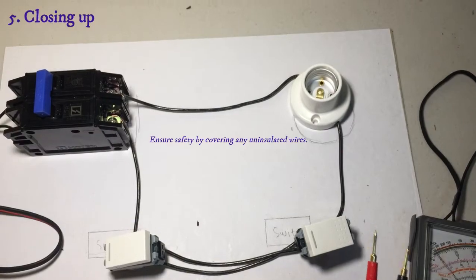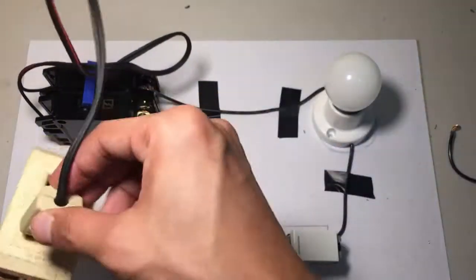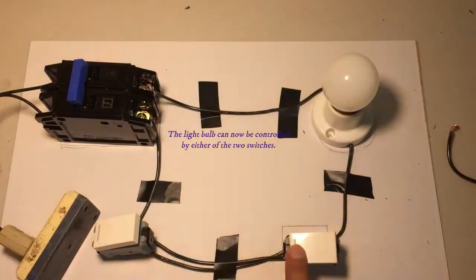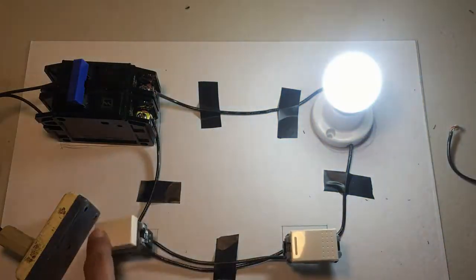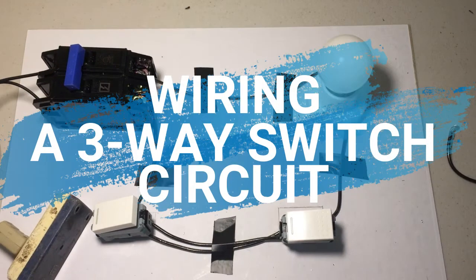Cover any uninsulated wires and tape them in place for safety. The circuit is now ready for use. Insert the light bulb and plug the socket into the outlet. As you can see, alternately pressing the switches turns the lights on and off. With this, we have completed wiring a three-way switch circuit.